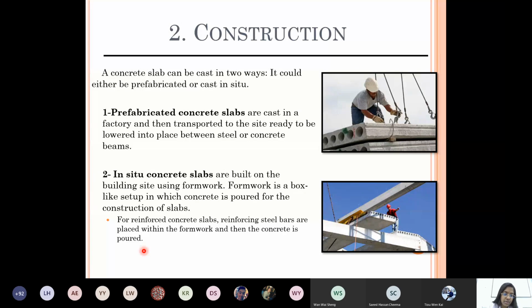All these things follow a procedure. Care should be taken for giving the proper cover, proper time for curing, and proper time for preparing and placing the concrete. These are all things you have to bear in mind. You should not leave the concrete for long after mixing and then start pouring. You should pour it immediately, before it hardens.